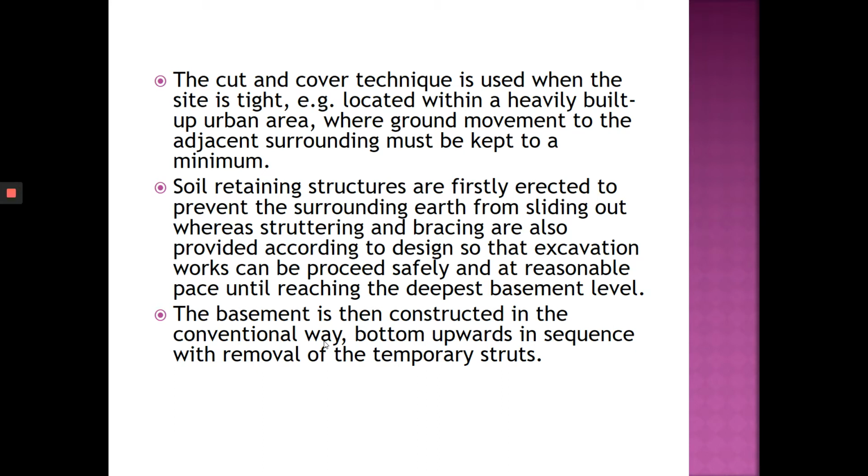Because when you do construction, you will have vibrations, you will have excavators, and all of these will make the ground move. You will also learn about this ground movement a bit in soil improvement, soil stabilization. Okay, the ground can move, and if you don't take precaution to do all this, like you don't really do retaining wall, you don't put sheet piles, you will create problems to the surrounding buildings.